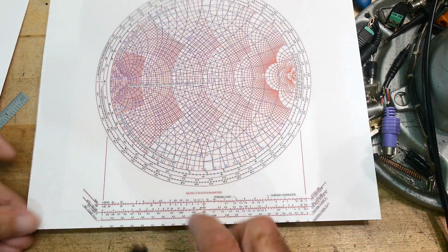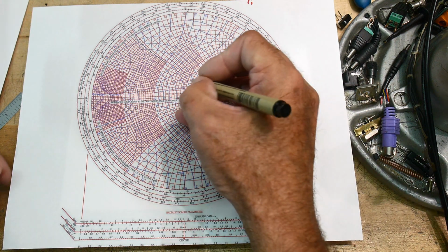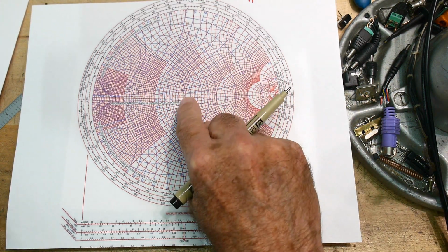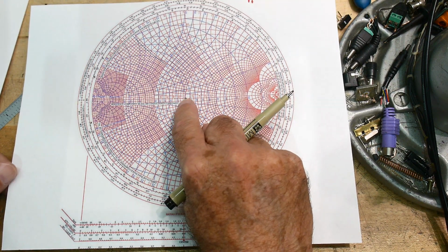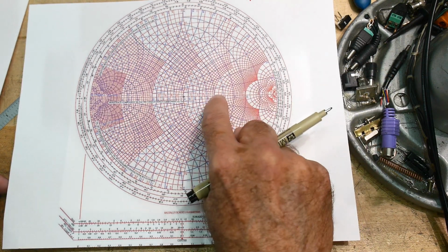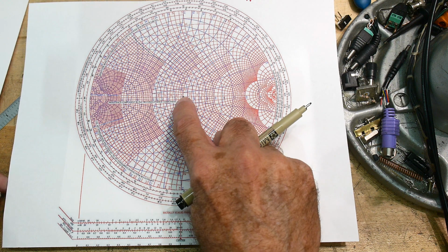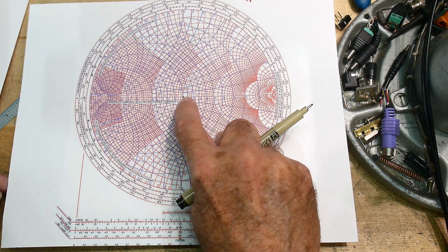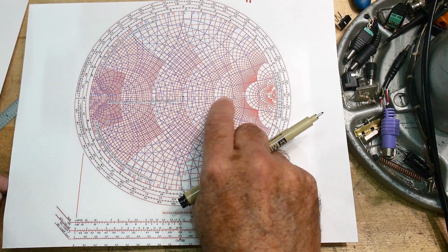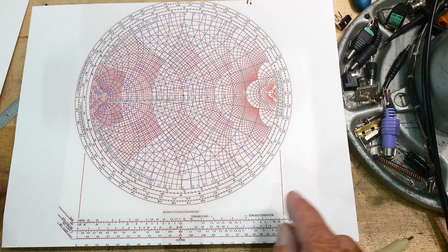These things at the bottom here, okay? Now, Smith charts are always normalized to 1. They always have just 1 in the center. But you get to normalize it to anything. You can just call this 50. And then here's 50, and then this says 2.0 for the R curves. So you just take 50 is 1. So 50 times 1 is 50. 50 times 2 is 100. So this is where 50 ohms is. This is where 100 ohms is. And then if you went up to 3, that would be where 150 ohms is. And it just gets bigger and bigger this way.